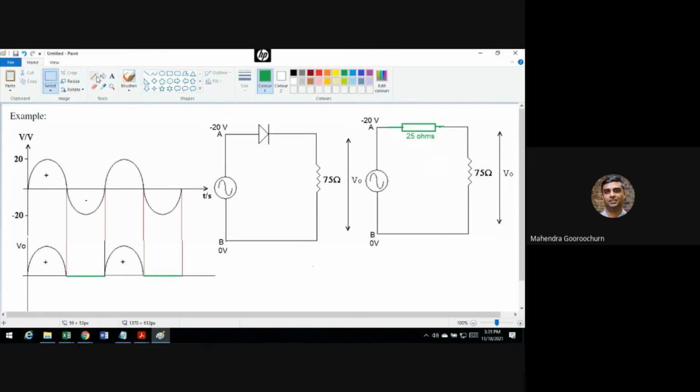How do you do that? 0.3 volts is very small, but if you have to draw it, you have to draw a line like this. I'm going to draw that in orange. So you draw a 0.3 volts line like this. It's only when you exceed that, so you have a small segment there where you have 0. Because it's not conducting at this point, this doesn't start straight away like this. It will have a small region where it's flat, and then it starts picking up.